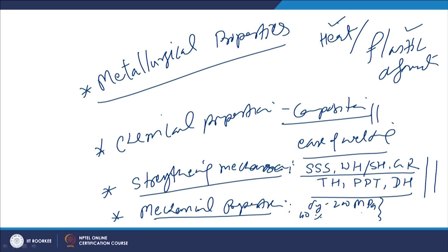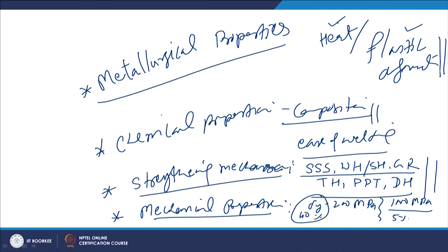this material will behave in a completely different way as compared to another metal system which offers a yield strength of 1000 MPa and a ductility of just 5% in terms of percentage elongation, because these two mechanical properties of the material will significantly govern the flow stresses or the flow behavior of the material, which in turn will affect the plastic deformation tendency of the material, and the change in the flow behavior and the plastic deformation tendency will affect the ease of welding using the deformation based approach, where either micro level plastic deformation or macro level plastic deformation is used.